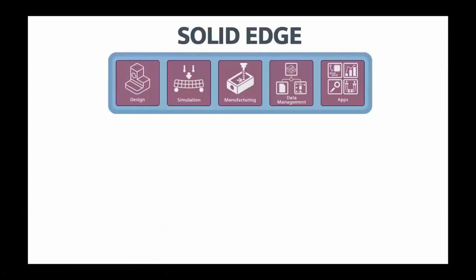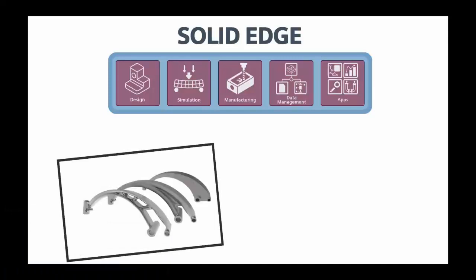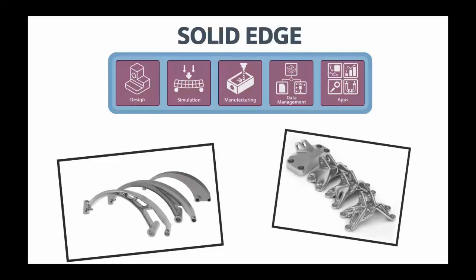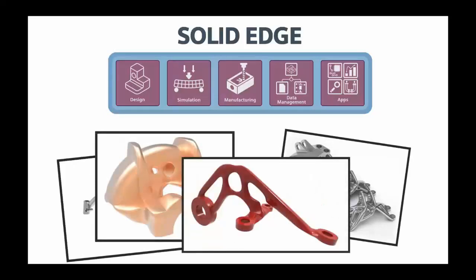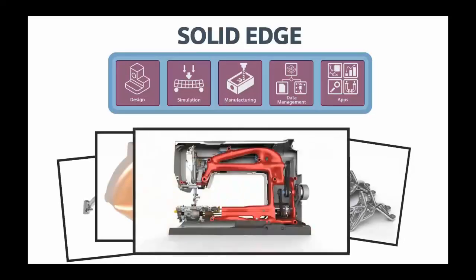Our tour today will be looking at some of the next generation design tools, which include generative design, convergent modeling techniques, and additive manufacturing. Generative design is a process whereby the computer will create an optimized design for us based on the use criteria of the part. This allows us to ensure our components are as lightweight as possible by minimizing material usage and saving costs, all whilst maintaining the structural integrity required.